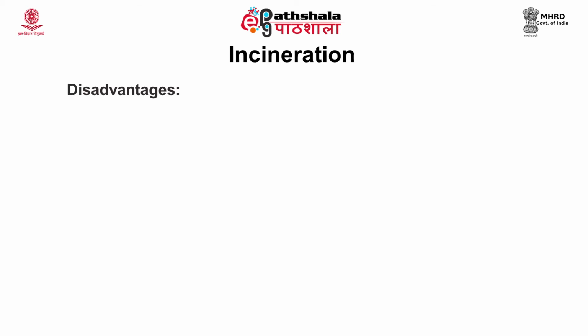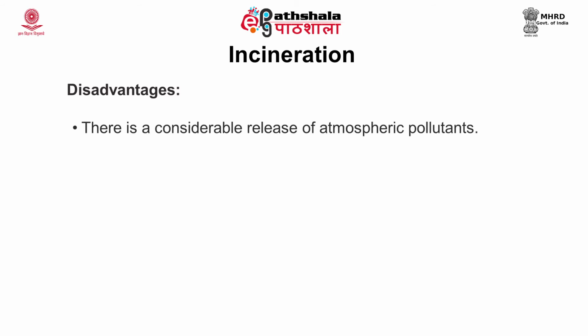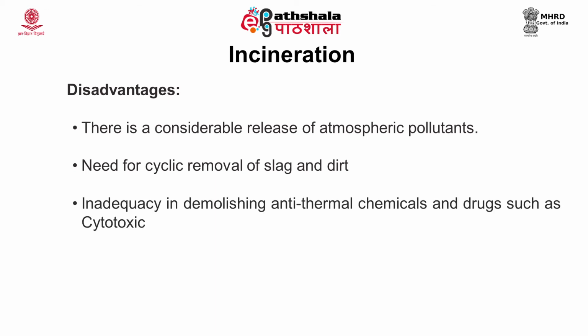Now coming to the disadvantages of incineration, there is a considerable release of atmospheric pollutants. Also it needs periodic removal of slag and dirt that results from incineration. Inadequacy in destroying antineoplastic chemicals and drugs such as cytotoxics is the biggest disadvantage of this method.